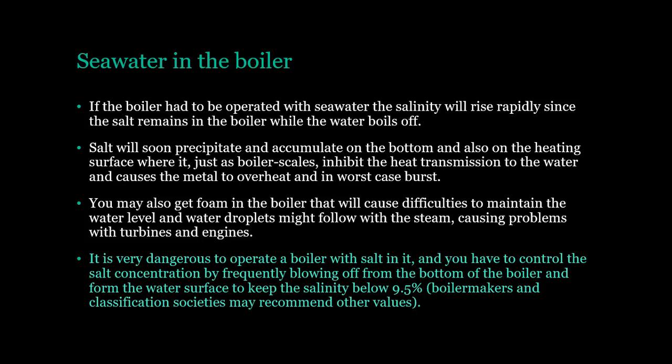It is very dangerous to operate a boiler with salt in it, and you have to control the salt concentration by frequently blowing off from the bottom of the boiler and from the water surface to keep the salinity below 9.5%. Boiler makers and classification societies may recommend other values.